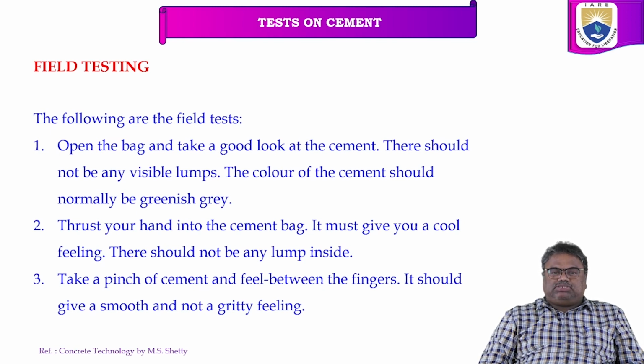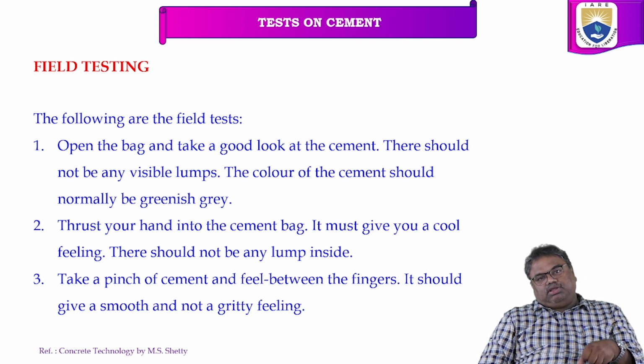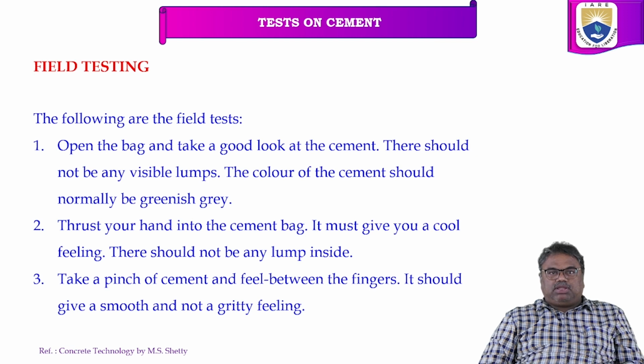The second one is to thrust your hand into the cement bag, and it must give a cool feeling. Just dip your entire hand in the cement bag. It should give a cool feeling. Then only you can say it's a good cement. And there should not be any lumps inside.